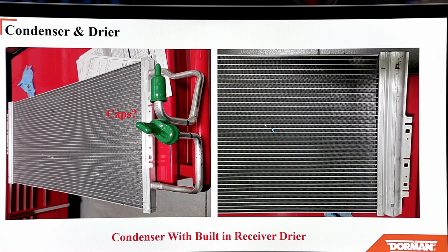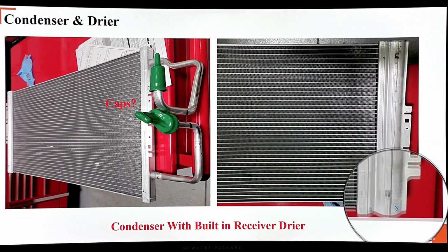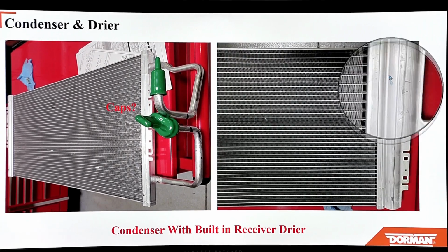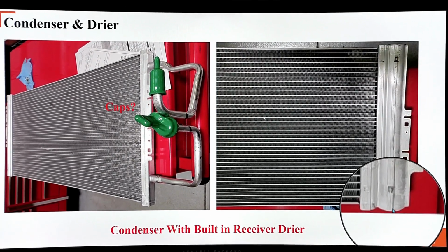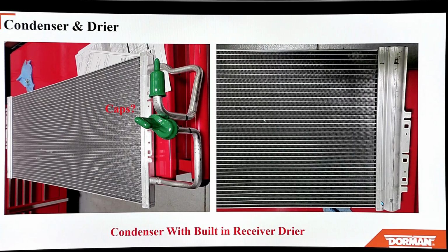Now here's a condenser, brand new. Here is where the receiver dryer is built in. Right under here, there's a little plug you take out. After all the refrigerant is removed, you take that out and you can put a new receiver dryer in.